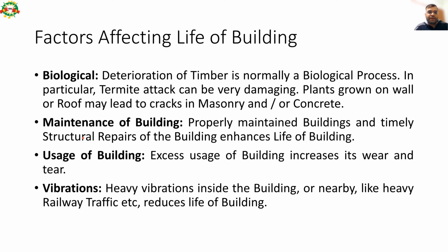So next factor is maintenance of building. Properly maintained buildings and timely structural repair of the building enhance life of the building. Use of building: excess use of building increases its wear and tear. Vibration: if some machinery with heavy vibration is installed in the building, or the building is nearby to some railway traffic track, all these factors cause reduction in life of the building.